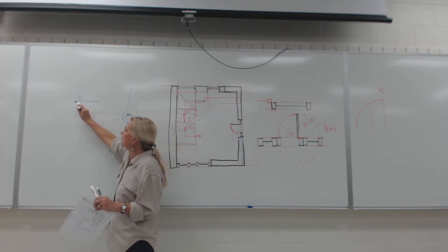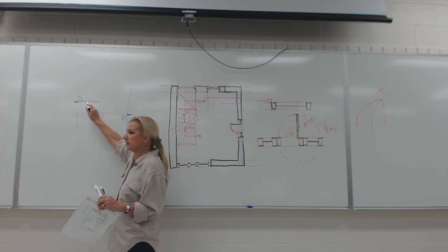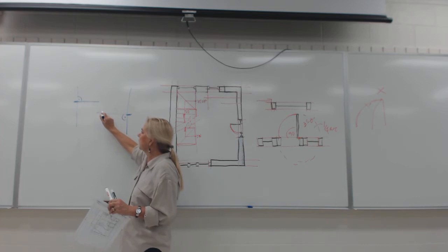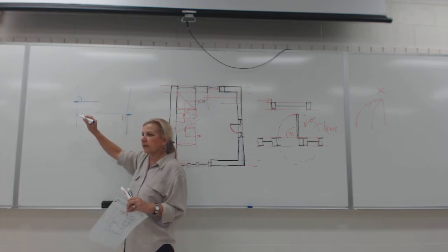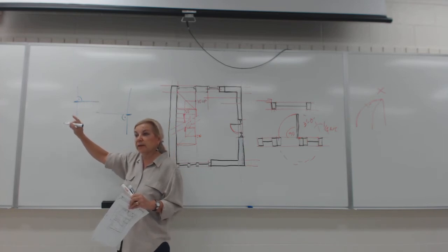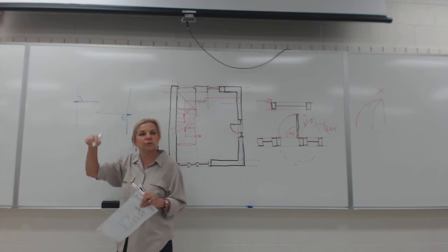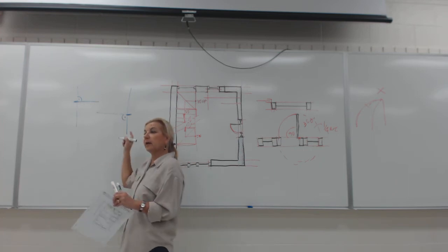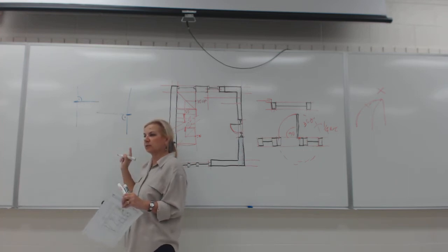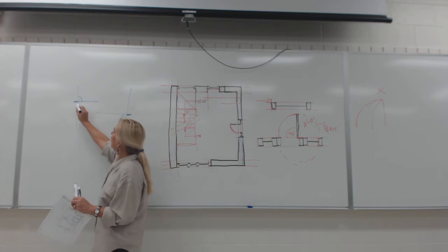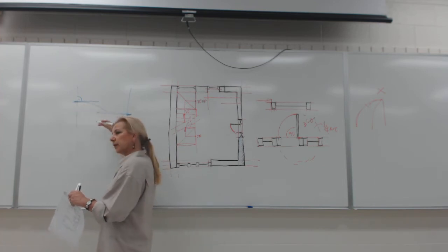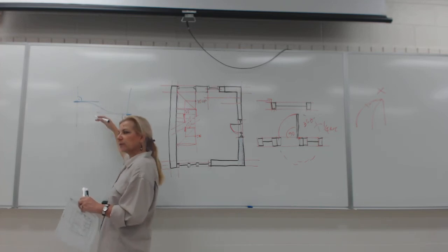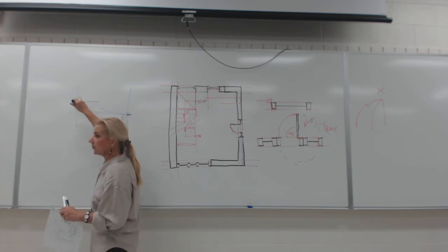In AutoCAD, you would start with ortho on to keep this at 90, and then you would turn the ortho off, and you would just put a couple points. And then you would make a P-line. And then you would edit it and change it to fit curve from contour lines and surveying, and split line to beautiful architectural curve. So what we're going to do is we're going to lay my flex curve and create this beautiful curve and basically copy it from the curve.